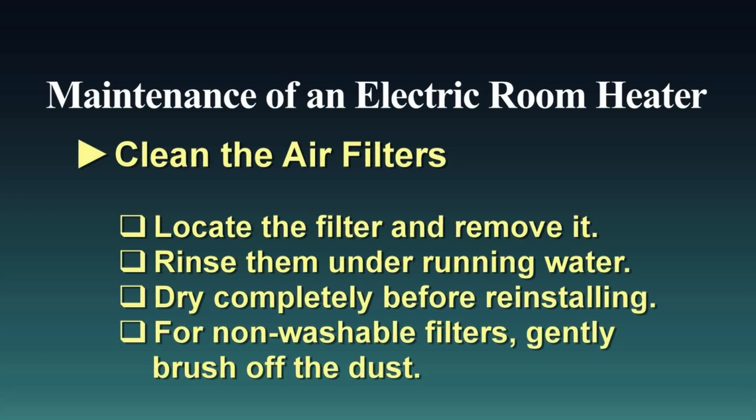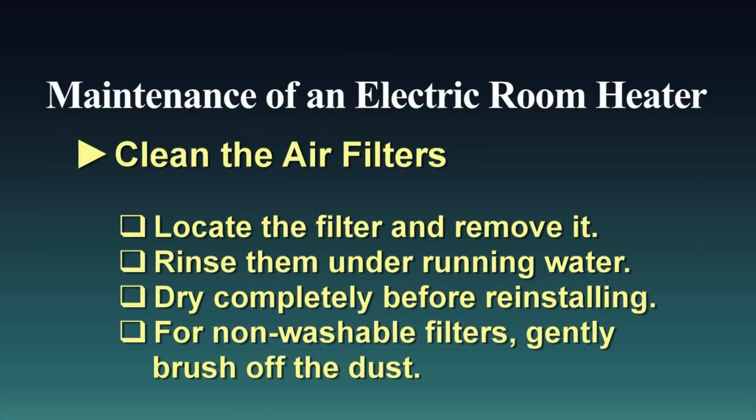Clean the air filters. Many electric room heaters have removable air filters that collect dust and other particles in the air. Over time, these filters can become clogged, which reduces the heater's efficiency. So, first locate the filter using the manual and remove it. If they are washable, rinse under running water and allow them to air dry completely before reinstalling.